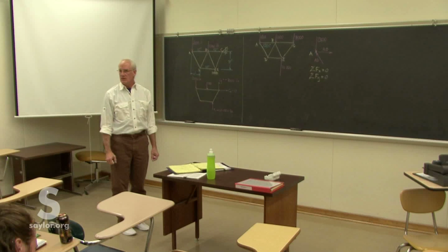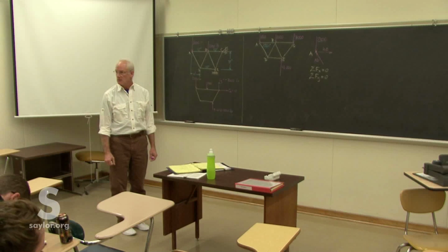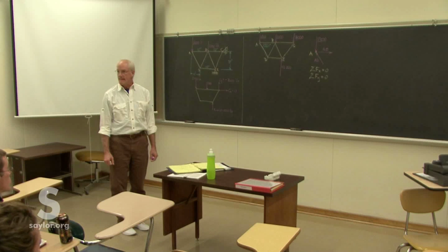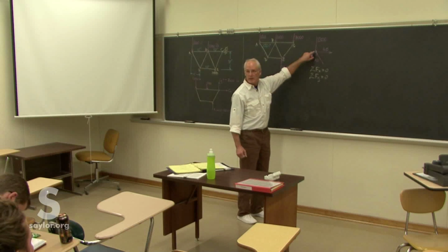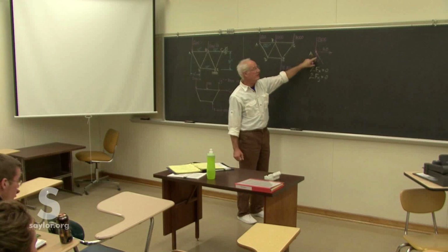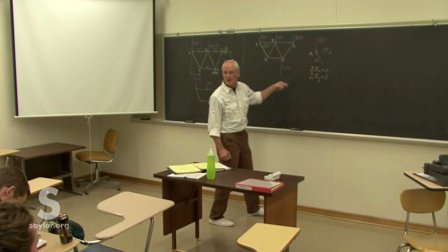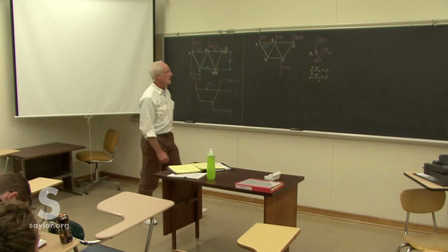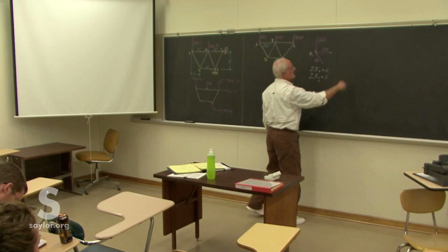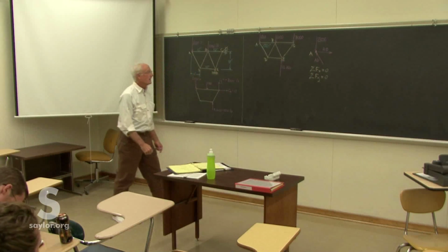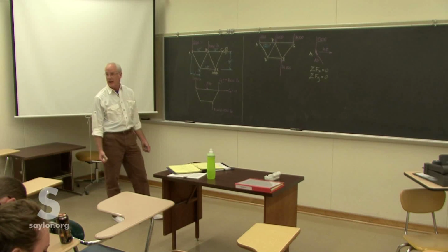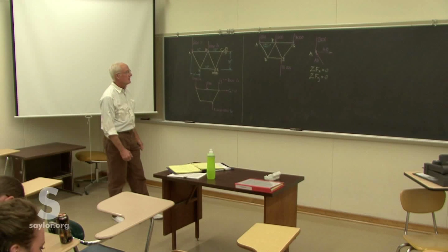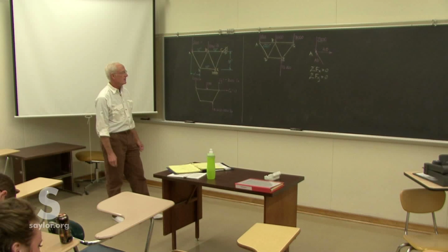What about using a moment equation? No need to go to point A. They'd all be zero. Well, there is no moment in this little sub-problem we have here. All forces go through the same point. None of them exert any moment. It's no use going over to some other point because that just complicates things. I guess we could do that. We can sum the moment about any point, even if it's somewhere else. But it's sufficient to do this, and we don't need to do anything more.